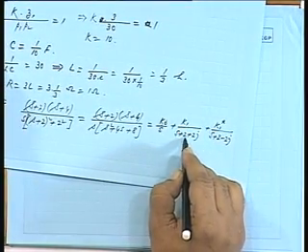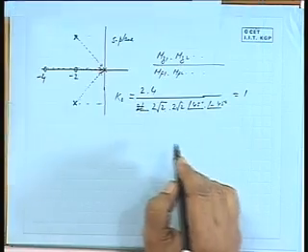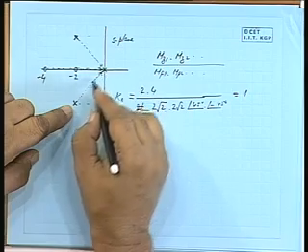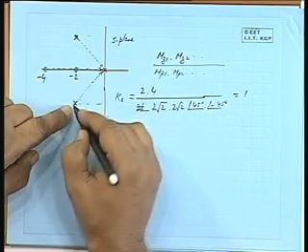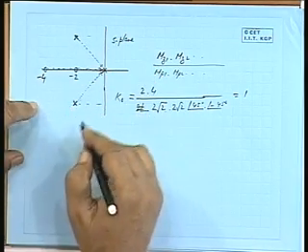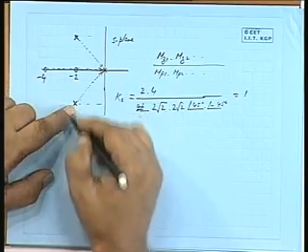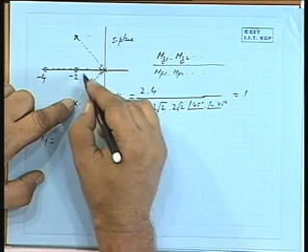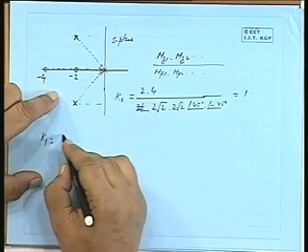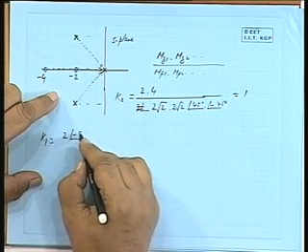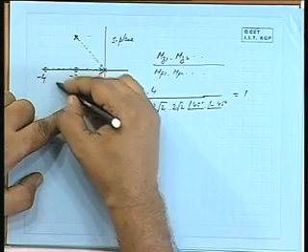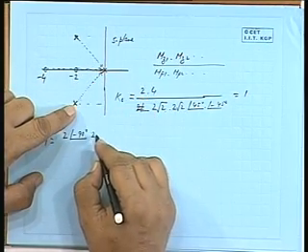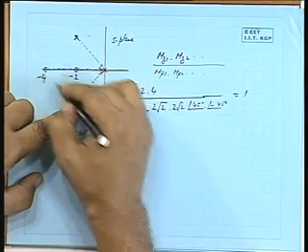So, the corresponding root is minus 2 minus 2j. So, minus 2 minus 2j is this one. So, draw all these vectors coming towards this point. What are the distances of the zeros? This is 2 and angle of minus 90 degrees. Is that all right? This one is 2 root 2, because this is 2, this is 2. 2 root 2 angle minus 45 degrees.